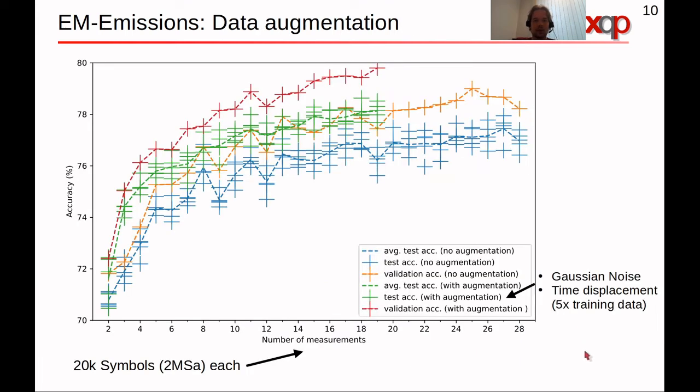I want to mention something about the amount of training data required for achieving this performance. We used 7 measurements to train at each distance and evaluate it again in a single shot. Here you can see multiple examples of test accuracy. This simply means that we record the test key trace several times, but test on each of them individually. So this is still a single trace attack, but it gives an indication of how stable these results are and what the measurement variation is.